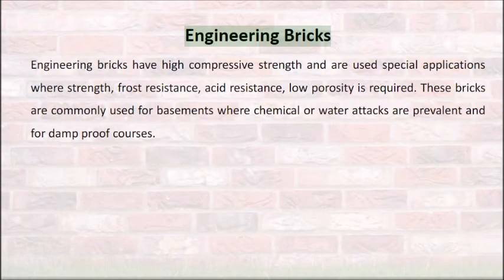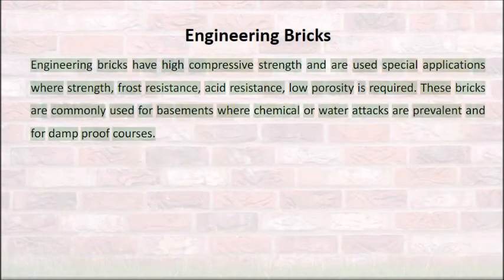Engineering bricks. Engineering bricks have high compressive strength and are used in special applications where strength, frost resistance, acid resistance, and low porosity are required. These bricks are commonly used for basements where chemical or water attacks are prevalent and for damp-proof courses.